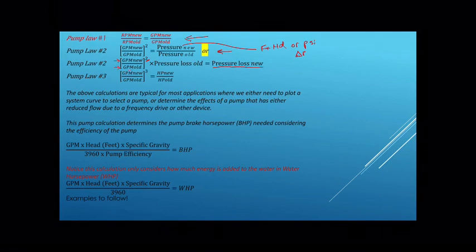And of course, the last one of the pump laws is pump law 3. That one identifies that as you change the GPM or the RPM, the horsepower will change, but it doesn't just change a little, it changes by the cube of that change.